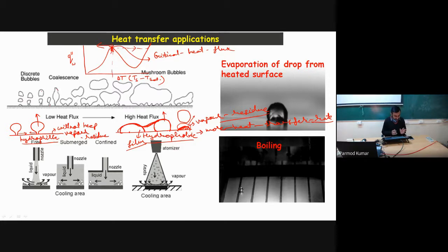Okay, so here we can see that the different surfaces have their different advantages and limitations. So if we have to design the ideal surface for boiling heat transfer, then we have to try a combination of hydrophilic and hydrophobic surfaces, which we call a biphilic surface, so that we have the advantage of the hydrophobic surface, which is a high rate of heat transfer, and the advantage of the hydrophilic surface, that we reach the critical heat flux very late.